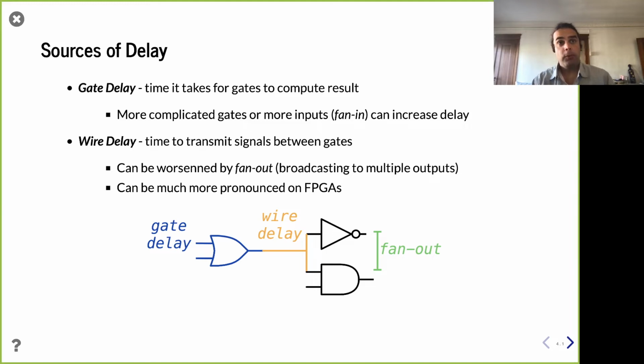So let's talk about delay. Where does delay fit into the whole picture? Remember we were talking about PPA last time? Power, performance, area. So it's performance, which corresponds to how long something takes to do. Now, of course, there's the delay it takes in a circuit, and there's also some notion of your clock frequency, your clock period, how much parallelism you have. For now, we're talking about just the delay, because that's going to impact us in many ways. So how long does it take a certain circuit to do something? Well, that's a delay.